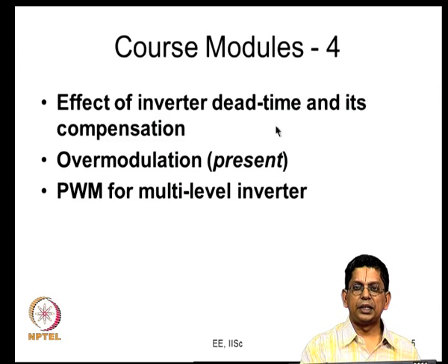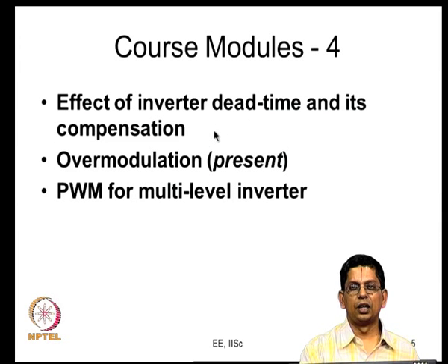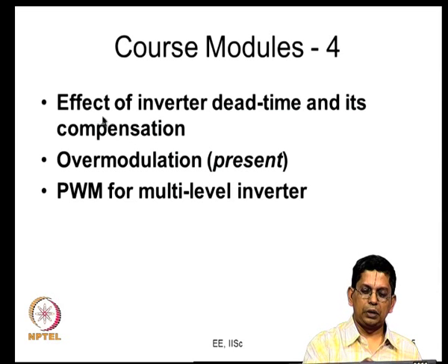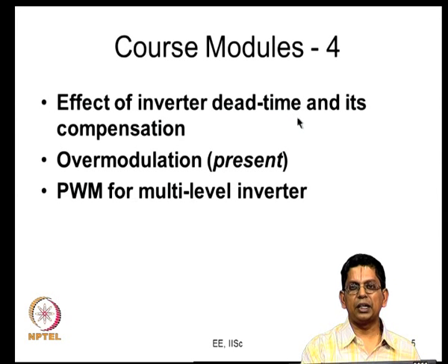We found that the dead time effect under a given condition changes from one bus clamping PWM to another, and also for the same bus clamping PWM the dead time effect varies from one power factor to another. The dead time effect and the compensation are just the other side of the coin. If you know the effect of the dead time, you can compensate for that. We found that it basically introduces a certain kind of error voltage. You can compensate for that error voltage by adding the negative of it to the modulating signal. So, though our emphasis was entirely on the inverter dead time, the compensation is just one step away.